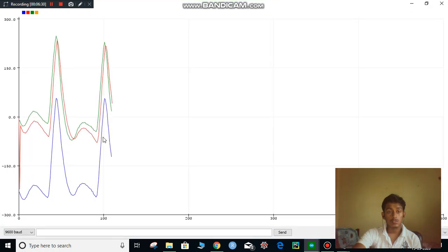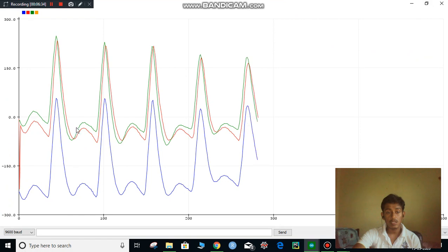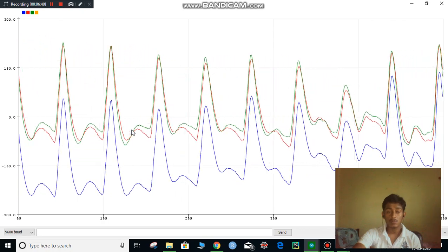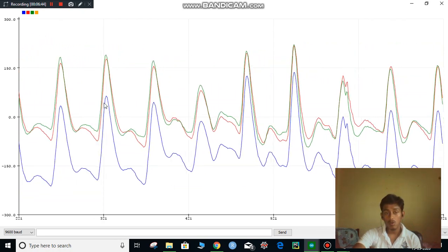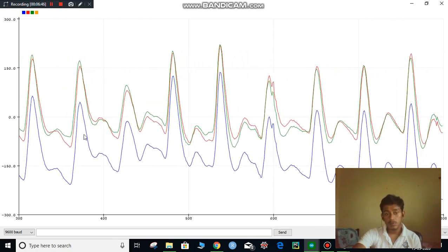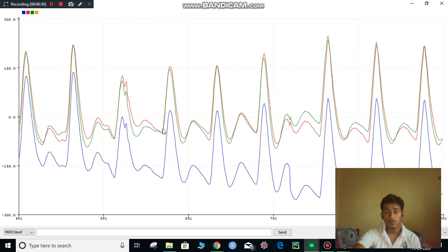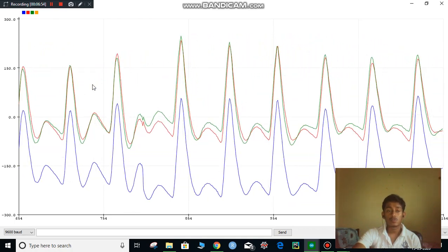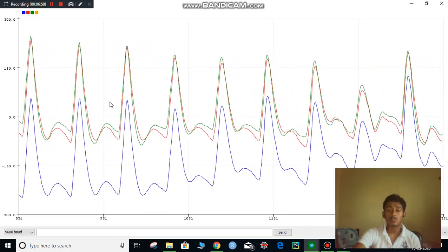As you can see from this, this is our actual signal, and these two are our outputs: the red one is our previous y output, and this is without baseline. As you can see, these are almost similar, but in some parts there is a little bit of deviation, because the pole zero placement method is not a perfect placement method, but it is nearly a perfect one.